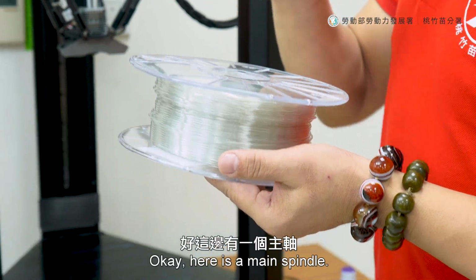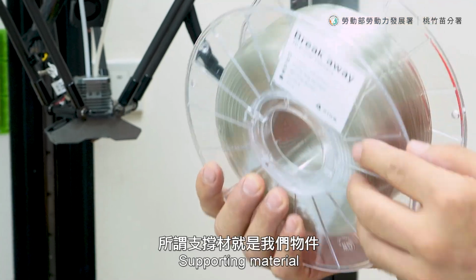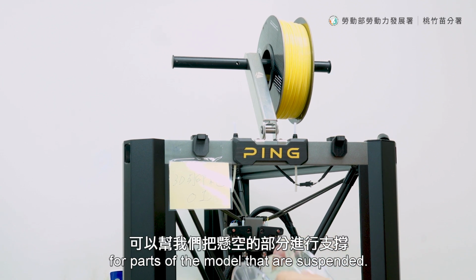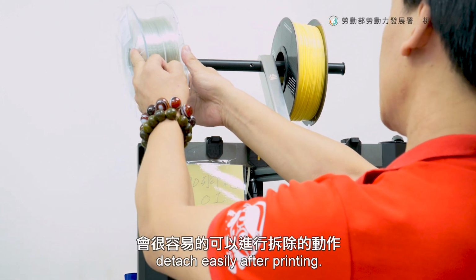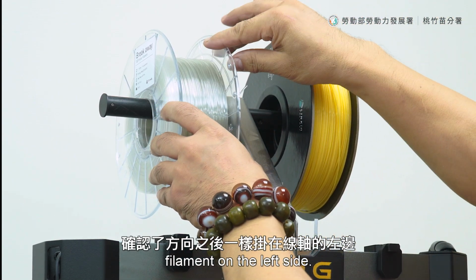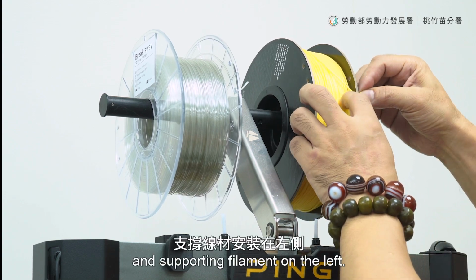Okay, here's the main spindle. We put it on. Then we install the supporting material on the other spindle. Supporting material is for hanging parts. This dual material printer provides structural support for parts of the model that are suspended. The two materials are different, so it's designed to detach easily after printing. We ensure the correct orientation before securing the filament on the left side. Alright, the main filament is put on and the supporting filament is on the left.